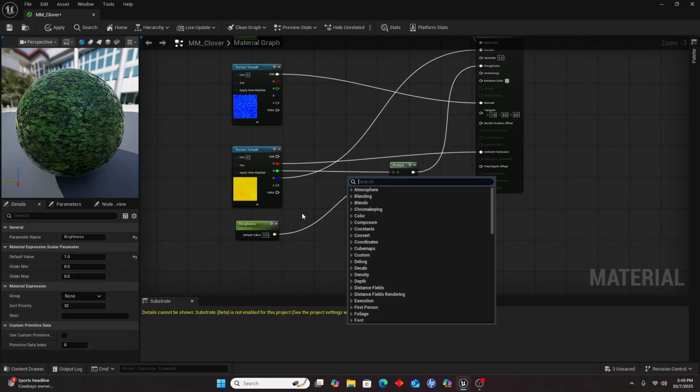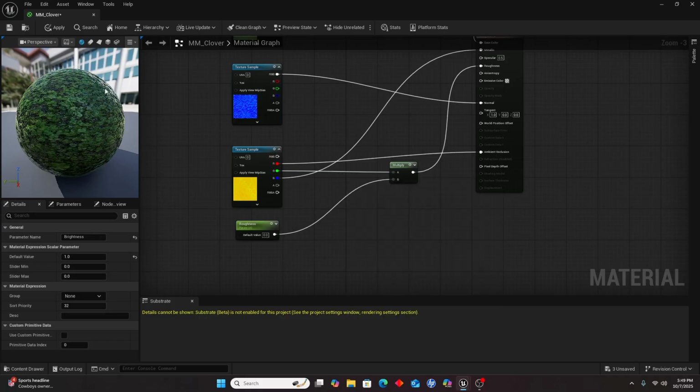And our roughness, you may have noticed that this looks very wet, and that's because our roughness right now is at 0. So we'll also default that to 1, and again, this is in consideration with the texture. So there is a shine to it because it is multiplying this number with the image texture. So I have to go up more, maybe to 10, to make this completely flat.